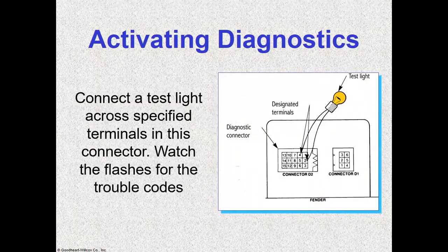Right? So connect a test light across specific terminals in this connector and watch the flashes for the trouble code.